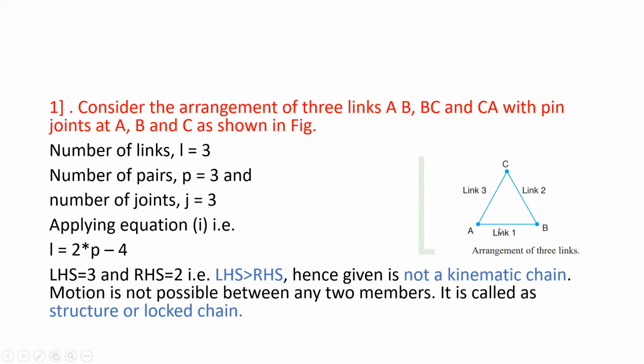See, when you will try to rotate the link 1, what will happen is that link 1 cannot rotate with link 3. Or in other words, the angle between link 1 and link 3 will always be constant. You cannot change it, you apply any force. Similarly the angle between link 3 and link 2 will not change, because no link will rotate or turn.